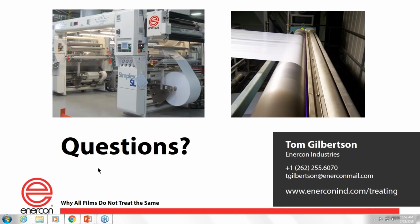And that failure can be for various reasons, one of which could be the corona treater or how the corona treater was used. But that would at least get you started down a path of looking for what changed. There are variations of that tape test. There's all kinds of resources out there for you to look at that, but that is just one example of a test method that you would use for determining adhesion in a printing application.